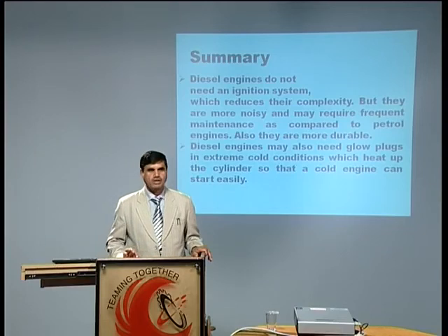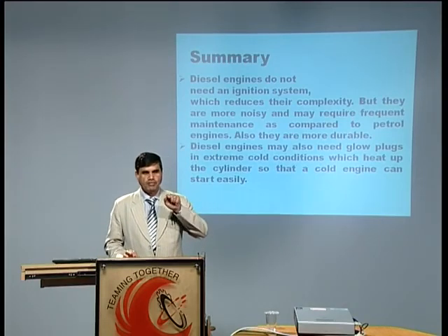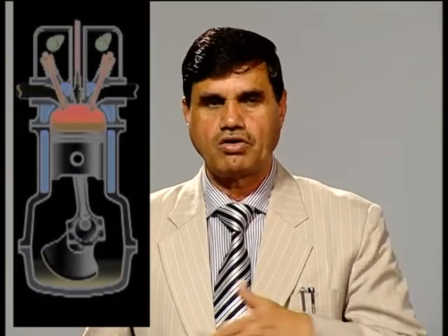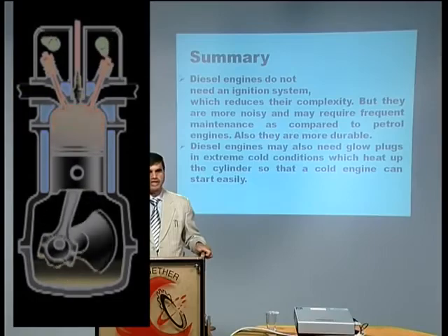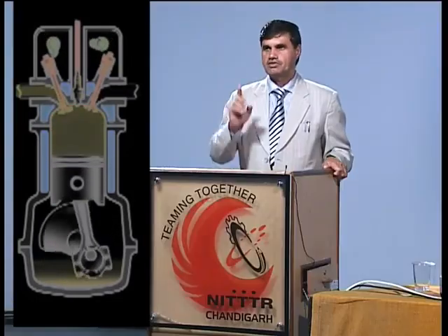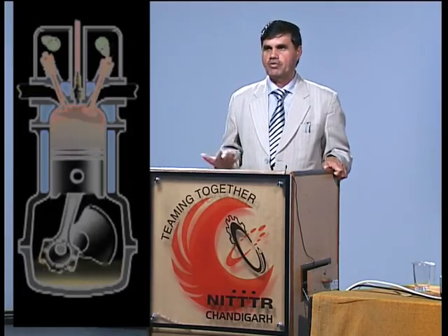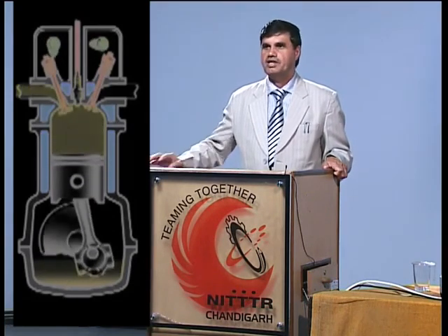Then in the case of diesel engine, for starting combustion, particularly when temperatures are low, early in the morning when we are starting the engine, starting becomes difficult. That time, for heating the air inside the cylinder, some heaters or glow plugs are needed, which are heating the air, and into the high temperature air we are injecting the diesel. So for starting purposes, some of the diesel engines are having glow plugs, but these type of glow plugs are not needed in the petrol engine.